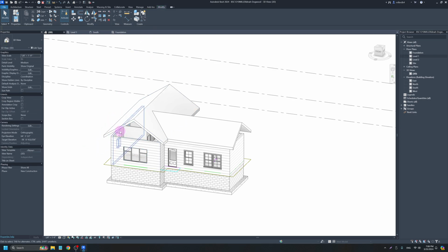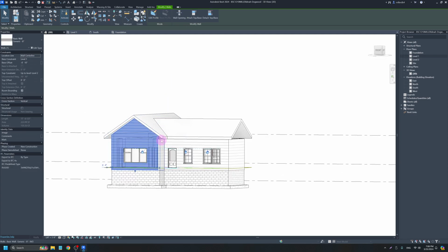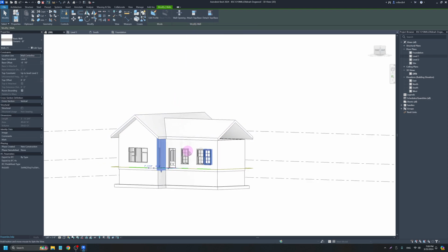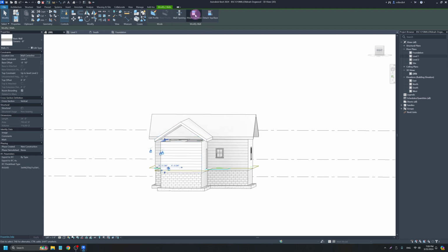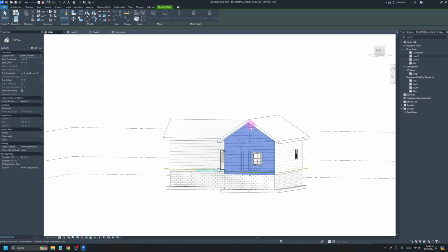And that is click on the wall, attach top to base, click on the roof. Click on the wall, attach top to base, click on the roof. We can't really do a chain, unfortunately, like with the tab tool, because we do have 2 different roofs. So attach top to base, click on the roof, click on this wall, attach top to base, click on this roof. But thankfully we don't have that many walls to attach to the base. And then this should be my last one.